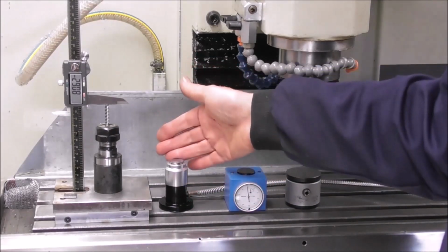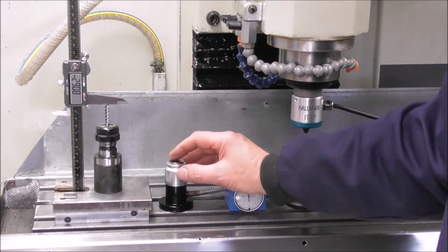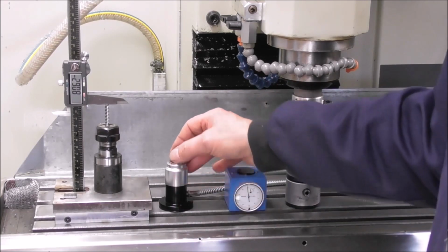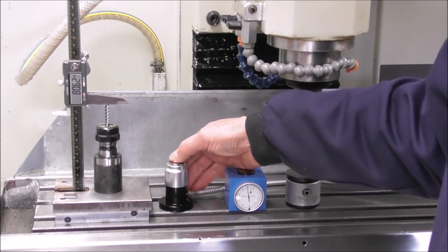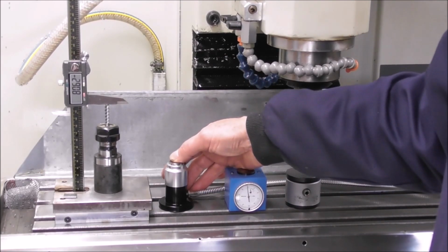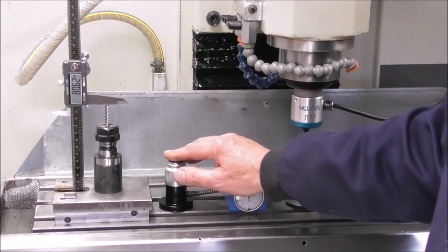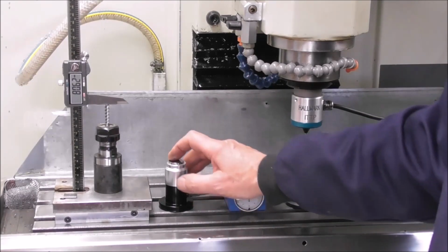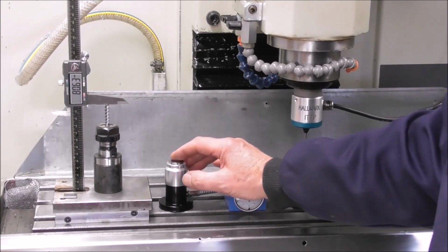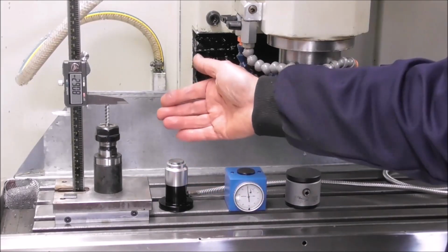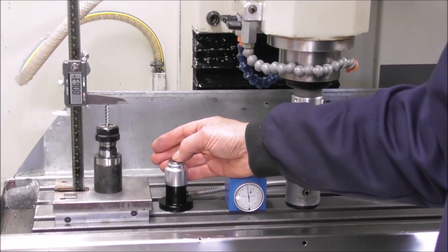There are ways to reduce the risk with an electronic tool setter. You can have a switch that does the software switching, and then further down, if that doesn't work for some reason, another switch, a backup switch, which connects through to your e-stop system and switches the whole machine off effectively into reset mode. Well, that's a safety precaution, but you could have problems with that, and it means hardwiring in 2 different circuits. And you probably want to leave it set on the table, and you've got coolant spraying everywhere. Is that going to be reliable long term in that environment? So there are concerns with an electronic tool setter.